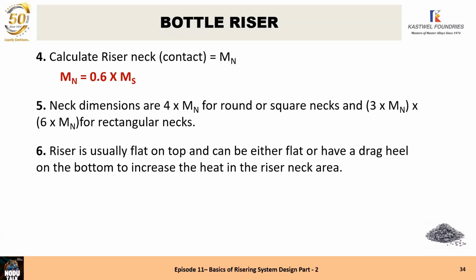Riser is usually flat on the top and can be either flat or have a drag heel on the bottom to increase the heat in the riser neck area. If the riser is not having the bottom in the drag, then you don't get enough heat in the riser. But I have worked with risers without the bottom, just the whole riser in the cope. The riser is usually flat on the top and can be either flat or have a drag on the bottom.